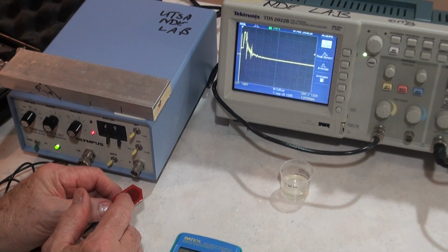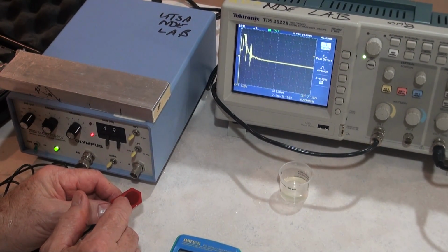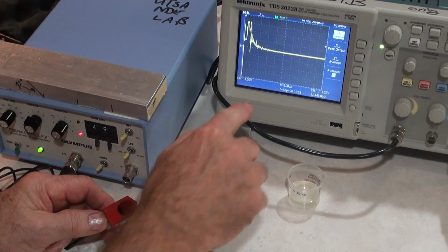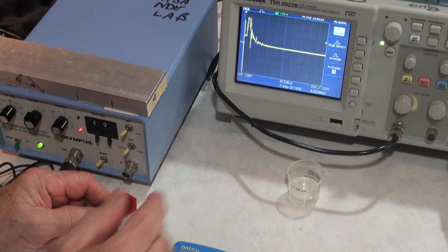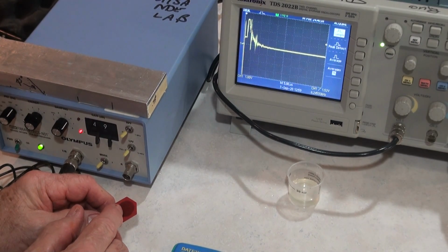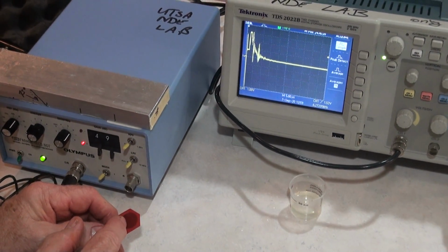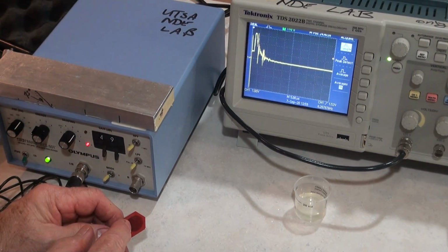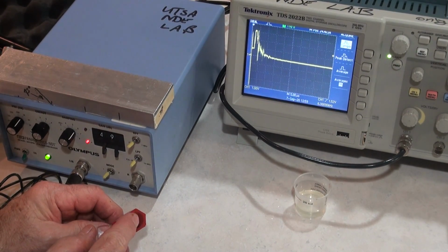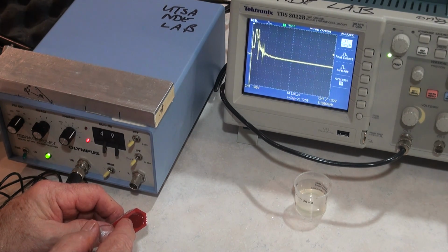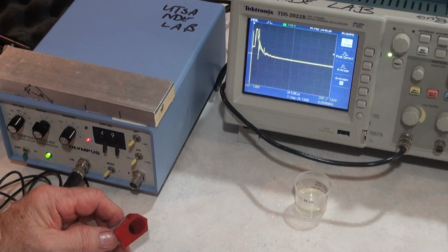Okay, and I want to measure that, and it looks like it's about 8 microseconds. The scale is 5 microseconds per major division. Okay, so for the first 8 microseconds, the sound from the transducer is in the wedge. So that's an important thing to know, because when we see a signal with our wedge, we're going to have to subtract that 8 microseconds out of the time to get the distance to the part, or distance to the defect.